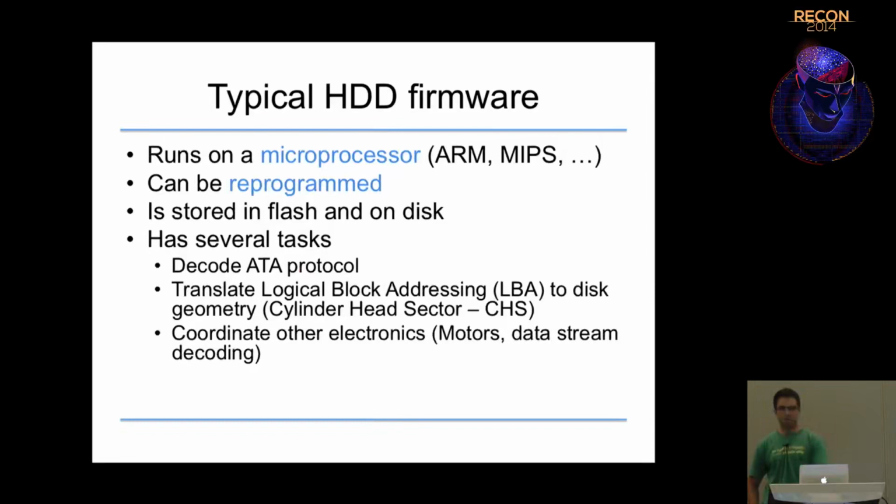And it has several tasks. It decodes the ATA protocol. This is the protocol that the PC speaks with the hard drive. It translates the logical block addressing to the cylinder head sector addressing. I don't know, people who are older than me probably still remember that you had to set cylinder head sector settings in the BIOS for DOS.